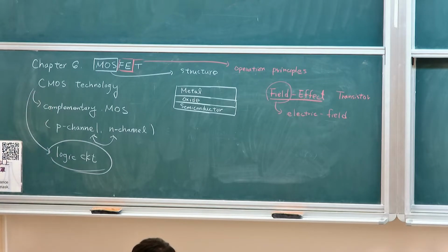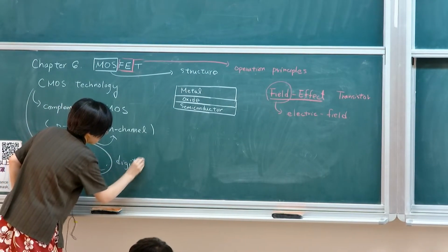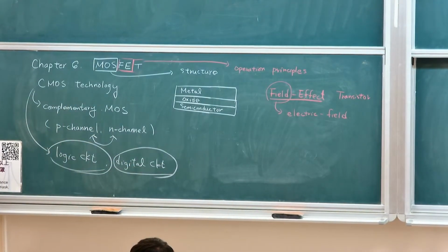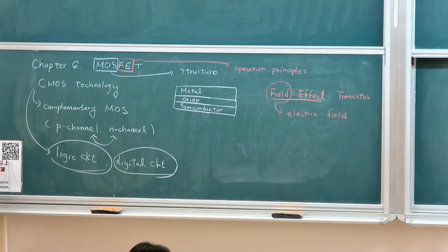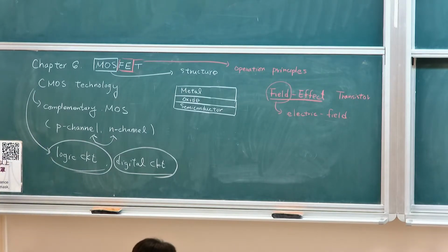Because digital circuits have become much more powerful, their peripheral analog components are also constructed with the same type of transistor, even though it's not that ideal for analog operation. Bipolar junction transistors actually have certain advantages in delivering high gain and high driving current for analog signals.